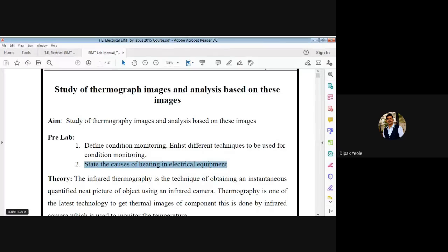Yes, so short circuit can be a reason for the development of heat. Yes, overload is there. Because of overload, heating can develop. Yes, surrounding temperature can be a condition. Obviously, inside Rajasthan, or you can say inside desert areas, the surrounding temperature causes excess heating inside the electrical equipment. So we have to think of that particular surrounding condition, and we have to install appropriate insulating material or appropriate conducting material inside the electrical equipment.